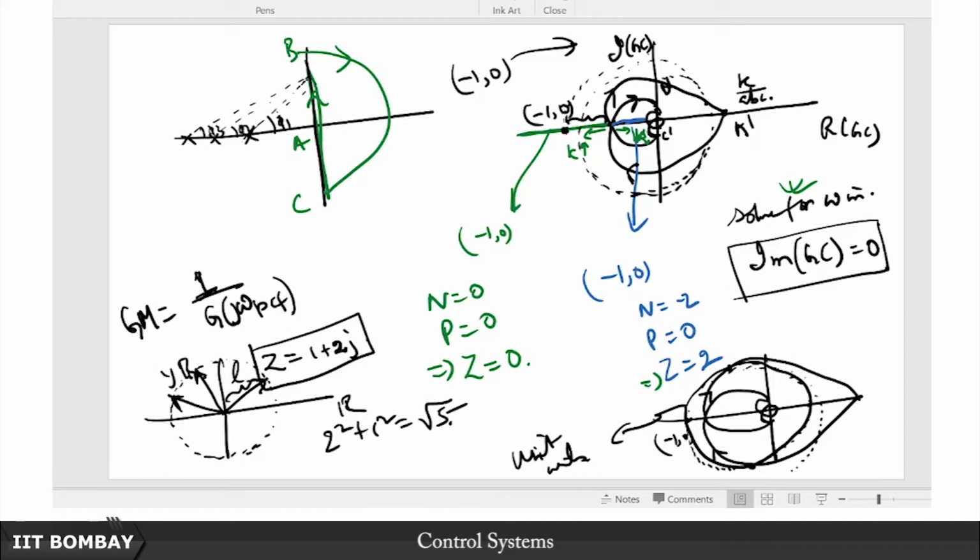So if I am going to just stretch around this Nyquist plot and rotate this, what is the phase at this point? This is called the phase margin, and why, I will explain in a moment. Let us say this is theta, the angle between this intersection point with the unit circle and this negative real axis. This is my phase margin, I am claiming. What is the interpretation of this phase margin?